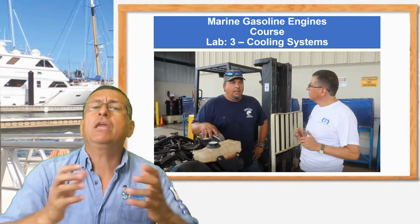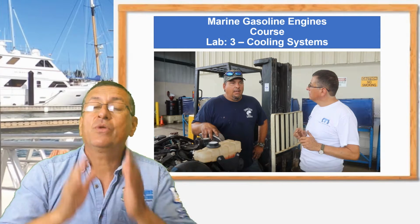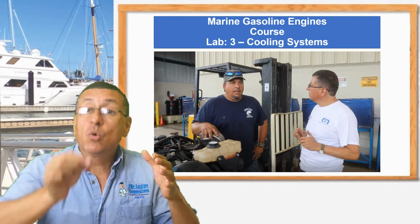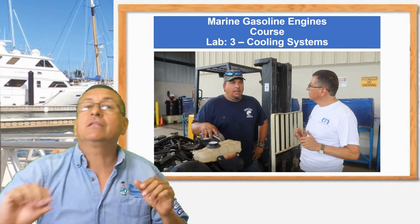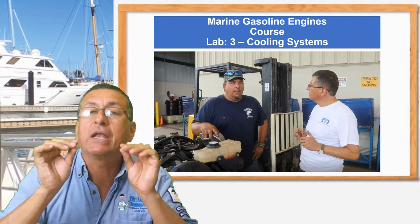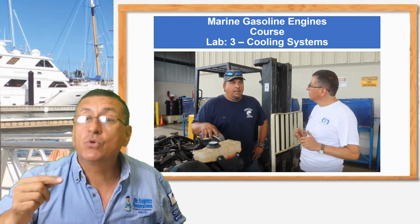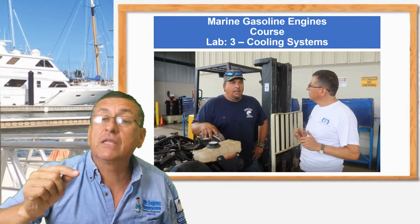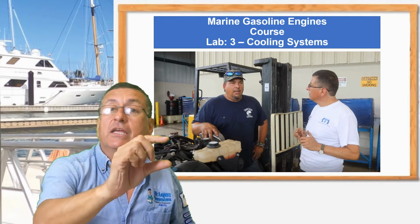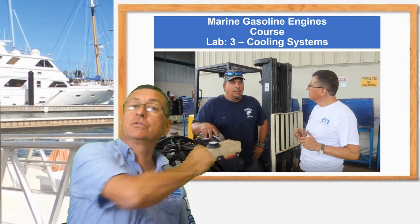And now for inboard engines with a closed system or heat exchanger system, we are going to check both sides. What is the path of the coolant in the block, and what is the path of the raw water through the heat exchanger. We are going to follow each one with your instructor. Your instructor helps you to identify the path of the raw water, at what moment the raw water enters the heat exchanger and goes out into the elbow of the exhaust.